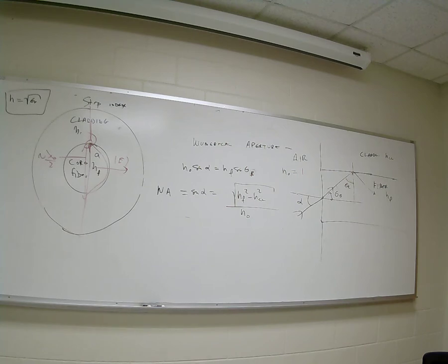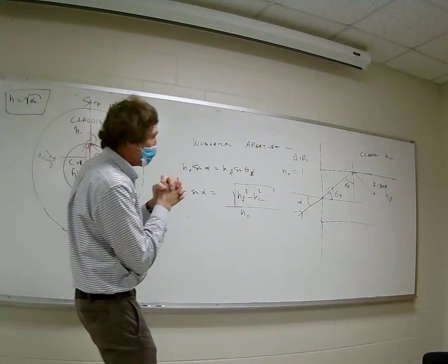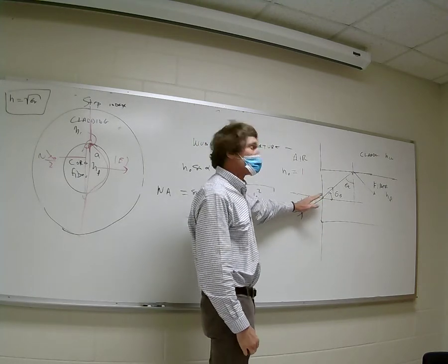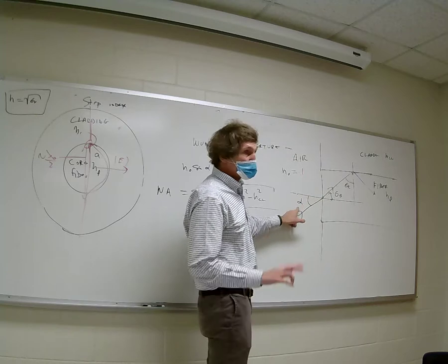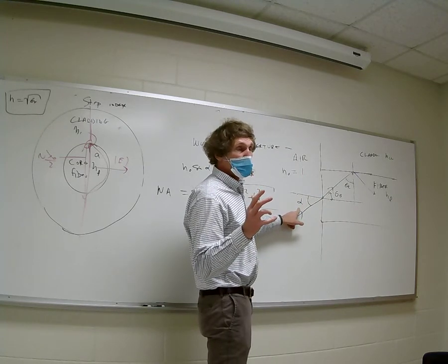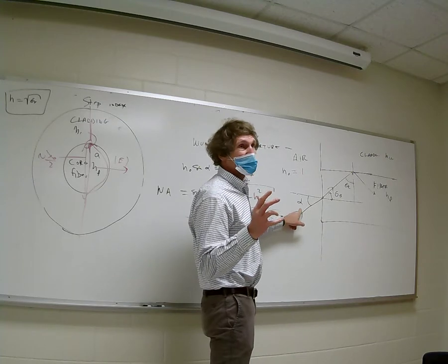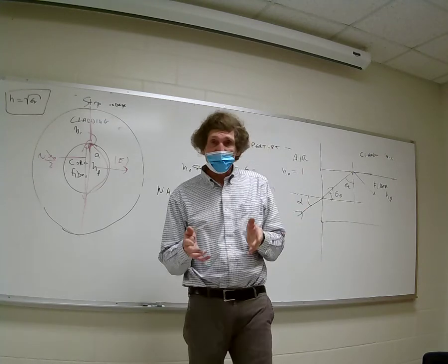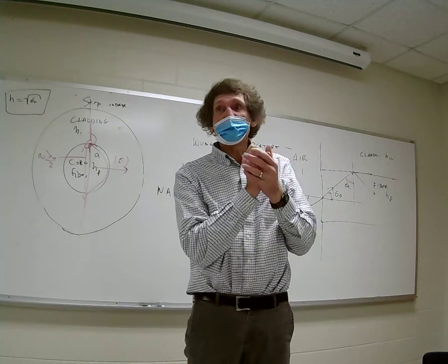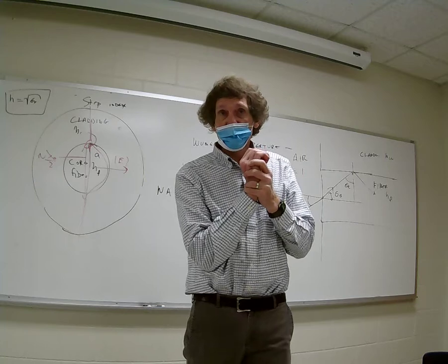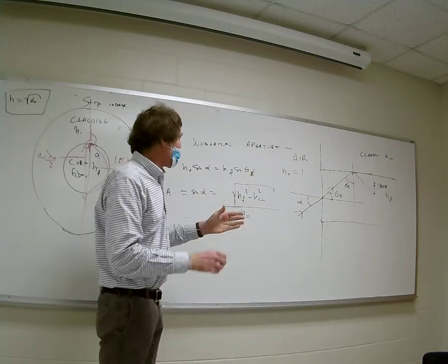So the numerical aperture tells you at what angle you have to be at. I mean, what's the maximum mismatch? If you get 5 degrees, you're doing well. All right, but you would like it to be 90, it's never going to be 90. So you get a numerical aperture as sort of a figure of merit of how much alignment is needed in order to get that light to go down there. You all follow me?